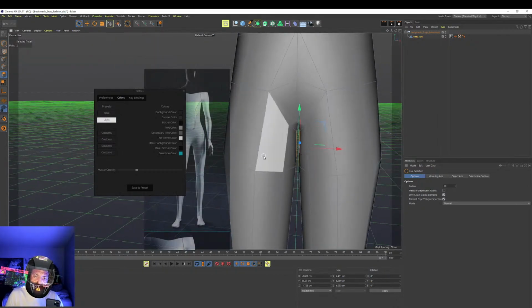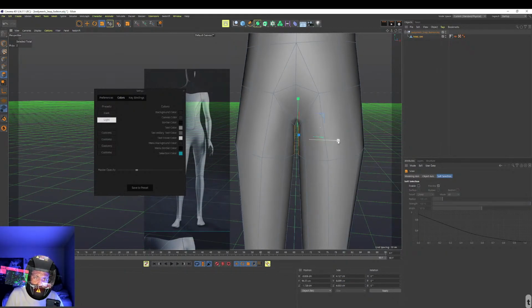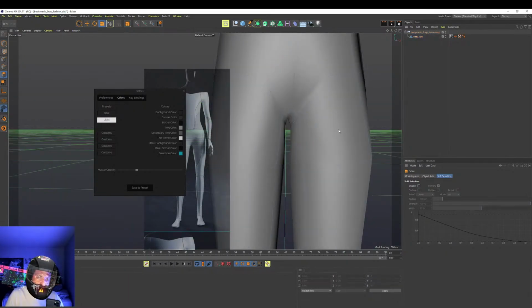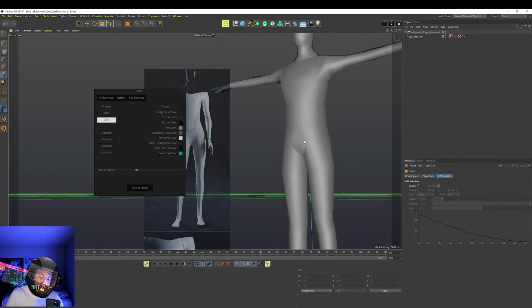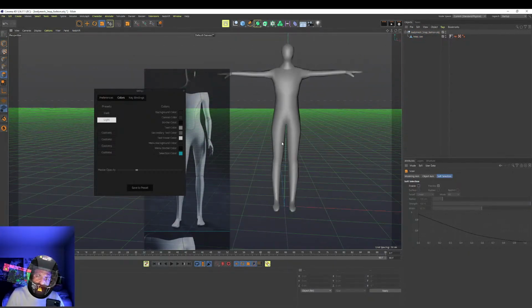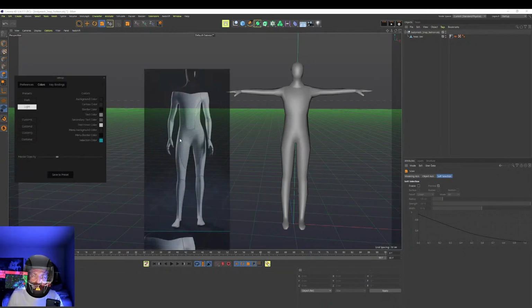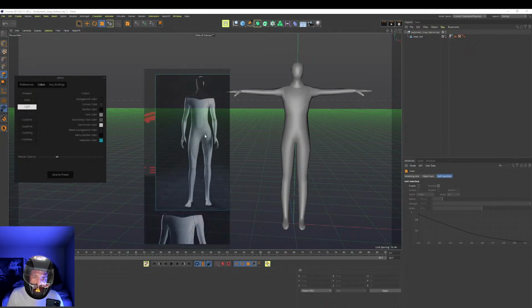And then I'm just going to pull these away from each other very slightly. It would just make the rigging software have less trouble rigging the groin by creating a little bit of space. When I'm modeling characters, I usually try to keep them in an A pose, where the legs are at a slight A shape, not too much, and it just helps with the binding and stuff. Okay, I think we're ready to go into ZBrush.